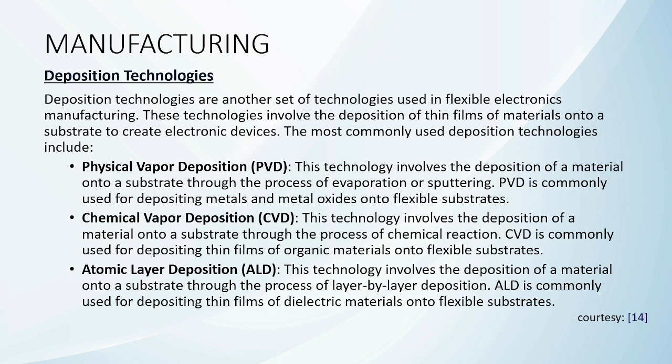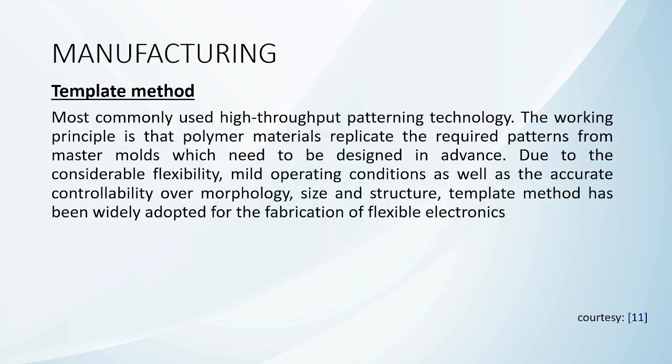Chemical vapor deposition. This technology involves the deposition of materials onto a substrate through the process of chemical reaction. CVD is commonly used for depositing thin films of organic materials onto flexible substrates. Atomic layer deposition. This technology involves the deposition of materials onto substrates through the process of layer by layer deposition. ALD is commonly used for depositing thin films of dielectric materials on flexible substrates.